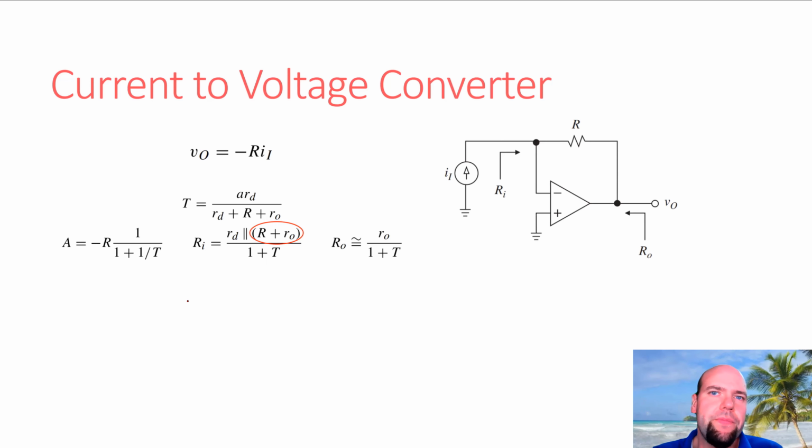So what if you've got a little tiny current, and you want to measure that current, or you want to have that current presented in a way that a microcontroller can read it, or some other analog to digital converter can read it? Usually you'd use a current to voltage converter. And these current to voltage converters are typically used for small currents. If you have a big current with a fairly strong source, there are sometimes easier ways to do this sort of thing. But for a small current, maybe from a very non-ideal source, you're going to want to use an amplifier circuit to boost that before your output goes to some other system, something like an analog to digital converter.